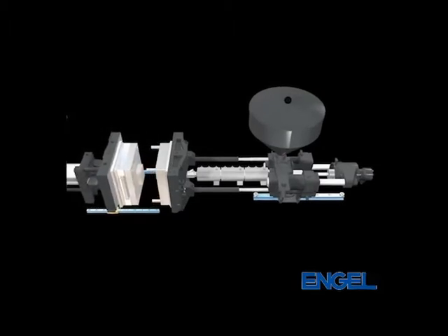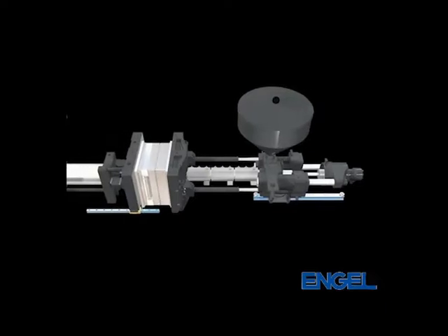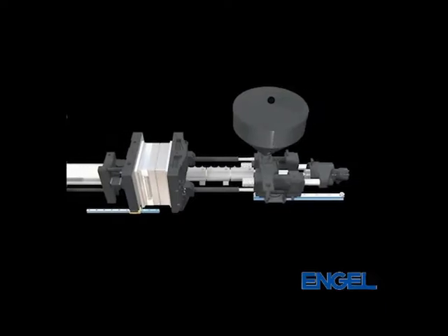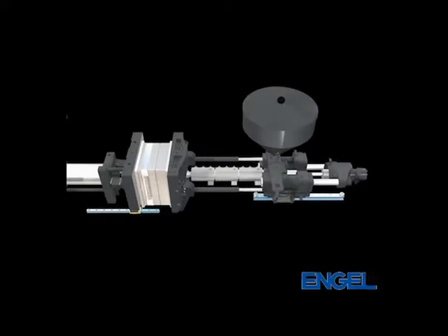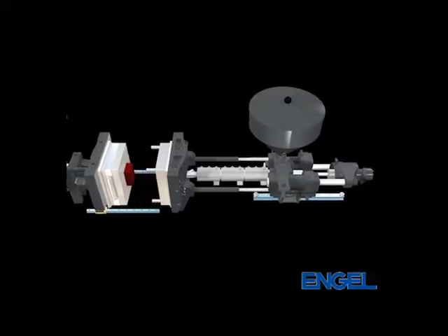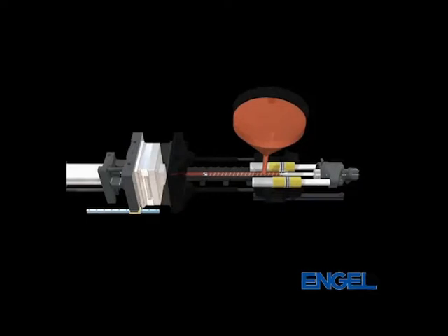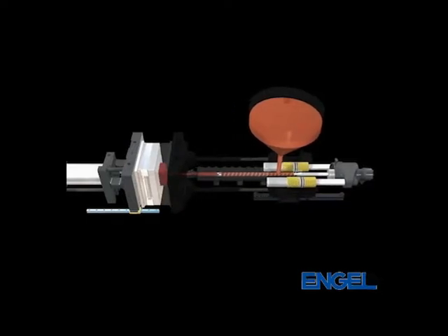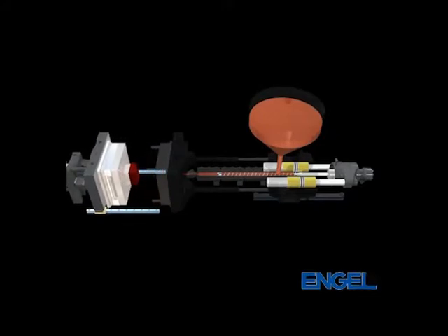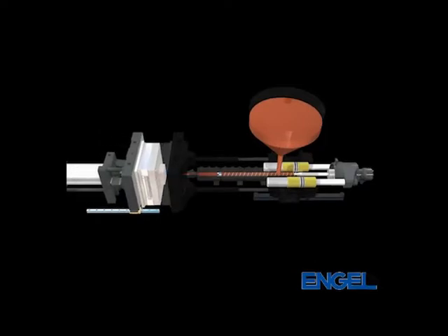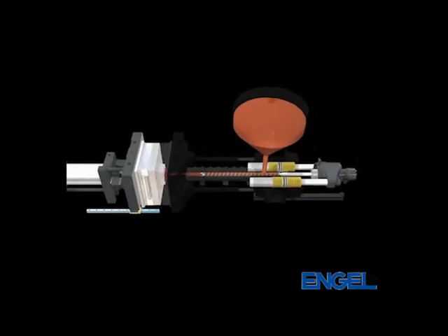So if we look first of all at the injection side of this, this is very similar to the extrusion process that Dr. Kelly discussed yesterday. Inside this heated barrel here, we have an extruder screw that's operating the exact same way as Adrian discussed yesterday. So we have a feed zone and a compression zone in order to convey and then melt the material. We also have a chilled area here to stop any problems with pellets spilling around the screw and not feeding forward, as was discussed yesterday.